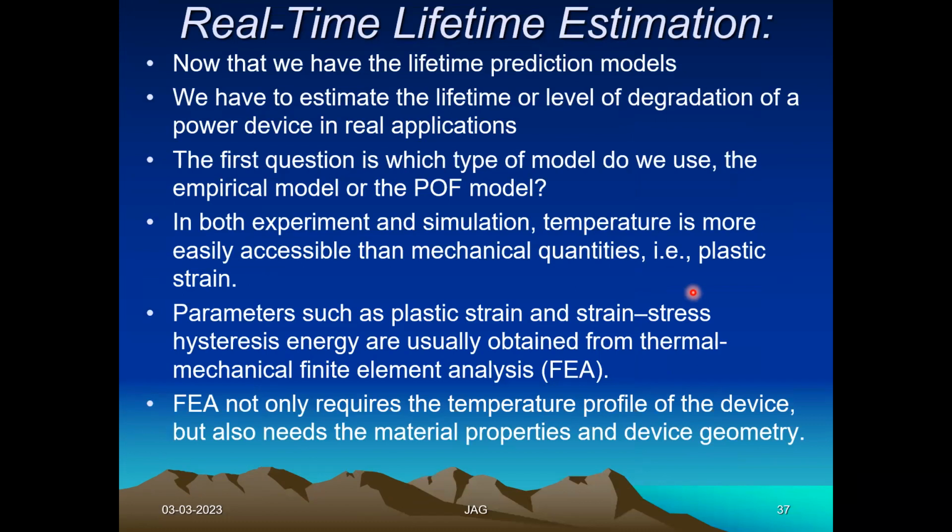So what we can do is predict the remaining useful life. Say I know that my vehicle has an inverter, and that inverter will fail in the next 5 days. If I know that well in advance, I can arrange a repair or a replacement. That is one possible method to avoid failure, that is, by using real-time life estimation. On the go, continuously, you monitor the device.